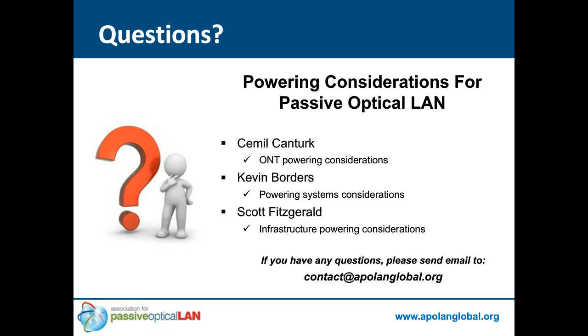And when you do that, you have parallel battery strings so that any one battery failure will not cause an outage. So if you lose AC power, or if you lose a rectifier, or if the system had a problem, it could create a situation. But you have batteries to back you up.